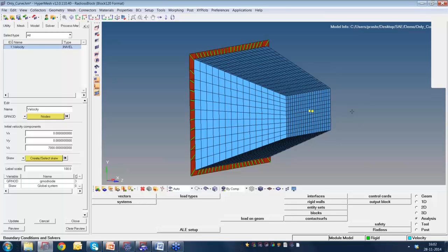So if I have to repeat the process again, I brought the CAD model and did the meshing. Since I had to do the solid meshing, first I did the shell meshing. Then using linear solid, I created solids. Then I created the materials and the properties, and using that, I created the collectors. Between two parts, I created the connections.